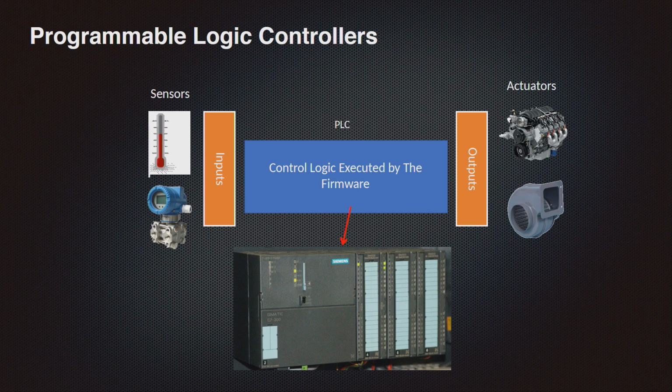And in the middle, we need some logic, and we encode this logic in programs, which in the PLC field are ladder logic programs or structured text programs, and those are downloaded onto the PLC, which then calculates the logic based on the inputs that it gets and puts out the outputs in order to steer such a process.